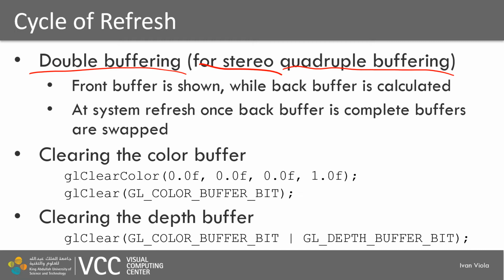Very often, the refresh of these buffers is synced with the so-called vertical sync. This means that the drawing on the screen will be synced with the way the drawing is done on the actual display. That way, we ensure that one consistent image is drawn and not some kind of tearing, where half of the display is shown with a previous image and half with a new one.